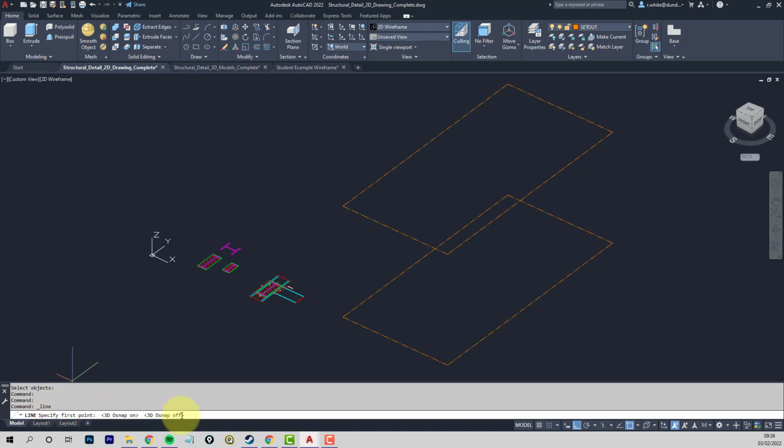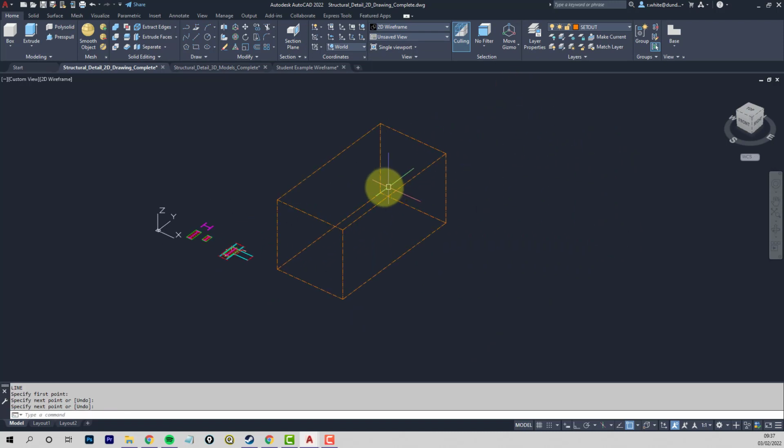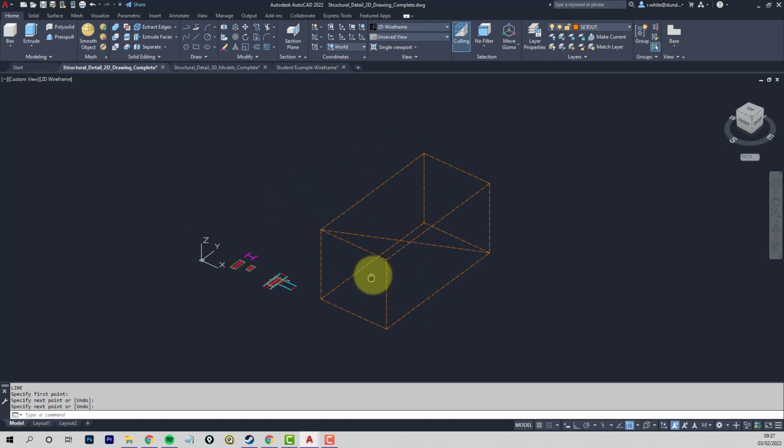Okay, so we're halfway through the line command here. It's saying where's the start point, where's the end point. Enter to stop. Ortho doesn't need to be on because we've got accurate positions to draw to. Okay, so I'll bring back the line command and just join these together. Okay, super simple. Now with a line we could draw diagonally through that object.